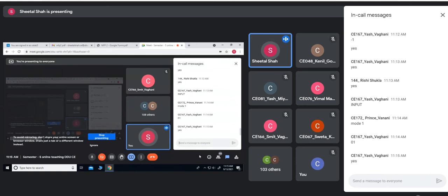Since we are using port B, as we know the lower order 3 bits are meant for the mode of port B, whether it is used as an input or output port, and the least significant bit is meant for port C's lower 4 bits. As we know, for port B, port C's lower 4 bits are used for the handshake. So even port C's lower 4 bits can be used as an input port. Hope everyone is clear. Okay, so this is a solution from my part of the paper.